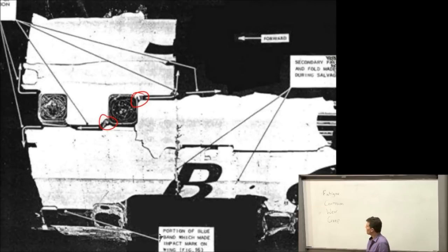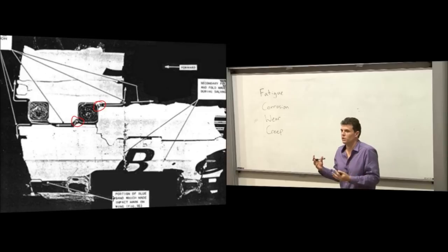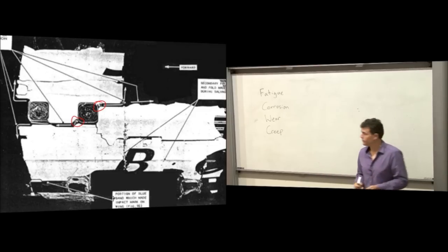Does anyone know why a window corner might? It's a stress concentration. So it was a high stress region, and that stress concentration didn't immediately show itself. You load the aircraft once and nothing yielded, nothing cracked. You load it a second time, third time, everything seems fine, and then all of a sudden these cracks are appearing. And that's a fatigue issue. When we load something statically, we may not see it fail, but if we repeat that loading over and over and over again, cracking can initiate.